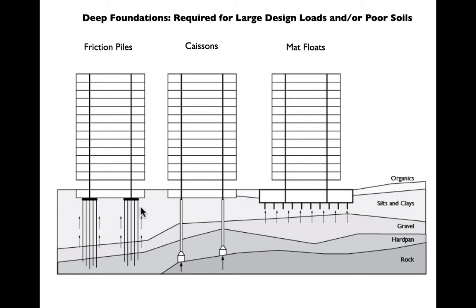the friction of the sand around the surface of the broomstick starts to build up, and the further the broomstick goes into the sand, the more interaction you have between the surface of the broomstick and the sand around it. Eventually that friction builds up to the point that you couldn't push the broomstick into the sand anymore. This is what we call a friction pile.